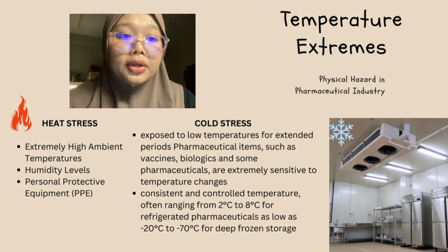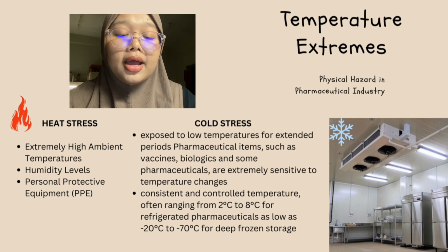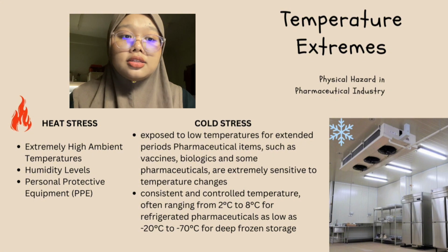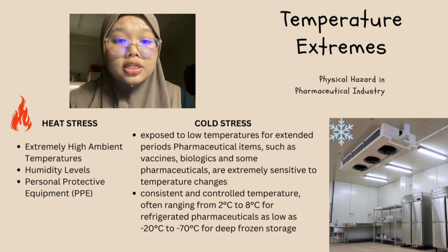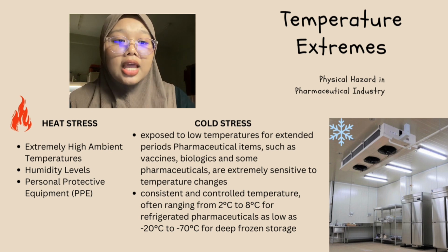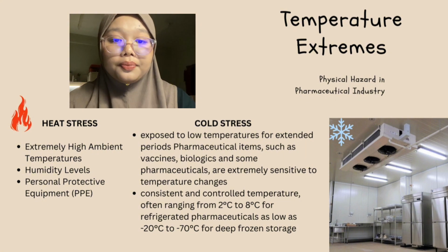Elevated body temperature can be caused by a combination of the ambient temperature, heat generated by manufacturing operations, and the insulation provided by PPE. Heat-related disorders such as dehydration, heat exhaustion, and even heat stroke can result from prolonged exposure to heat stress. This is especially important in pharmaceutical production regions where procedures generate a lot of heat and in facilities that don't have enough ventilation.